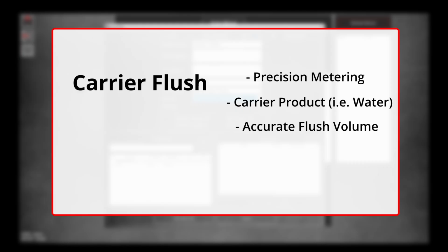Carrier flush is most useful at facilities with multiple injection points feeding into a shared carrier line. Sites with simpler plumbing may not need to use this feature. Carrier purge clears remaining product from the carrier line using air, pushing it back into the truck. This process is automated and replaces the manual purging method operators may already be familiar with.